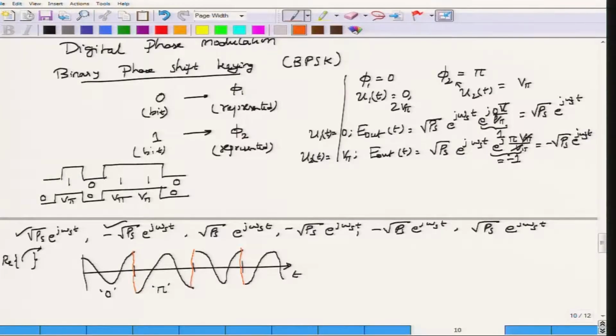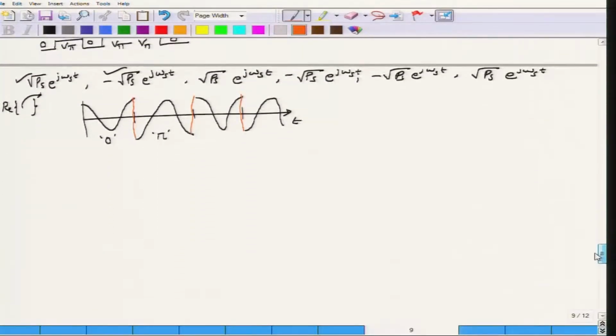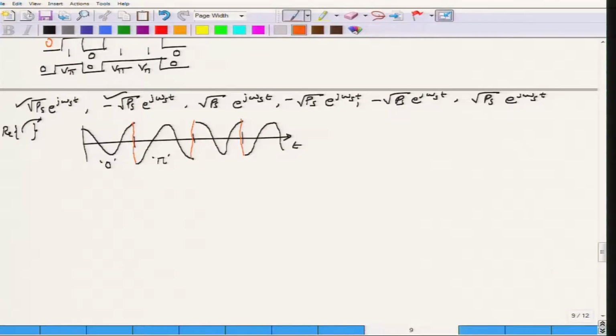Well, it turns out that what you are interested in is not these amplitude variations, but rather the phase, and when you perform the appropriate phase detection on this waveform, you will be extracting the phases 0, pi, 0, pi, pi, 0, which are then mapped to bits 0, 1, 0, 1, 1 and 0. So, although the modulation is digital, the final waveform that will be transmitted over the fiber is actually an analog waveform. Okay. So, this completes our understanding of BPSK and phase modulation.